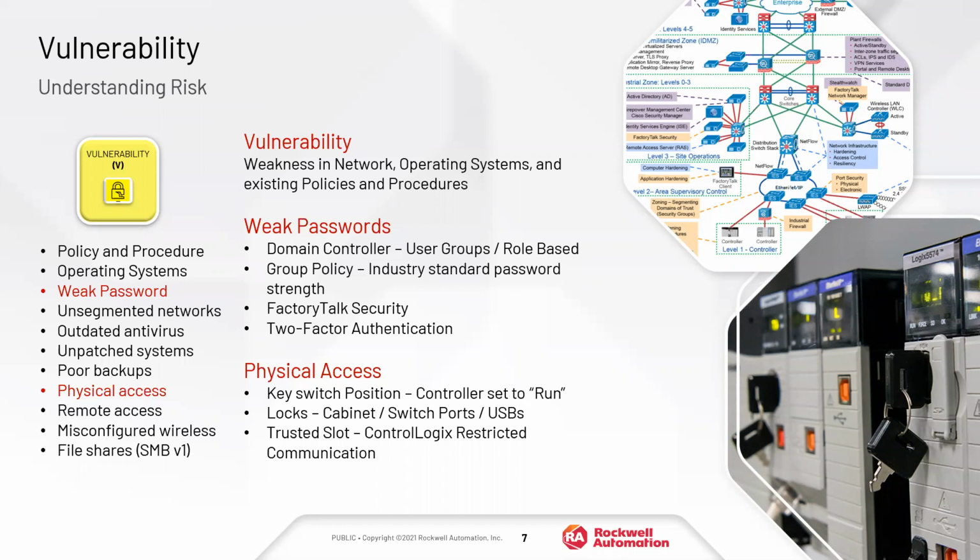You would make that call at the beginning when you set up the controller, and it could easily be used to, let's say, disable the USB access port as an option. This is built into Studio 5000. It's part of FactoryTalk Security. It's available on virtually any ControlLogix family. It's just one of those things where traditionally we don't see that turned on very often, but it is definitely an option. We can always provide more information to you guys if needed.